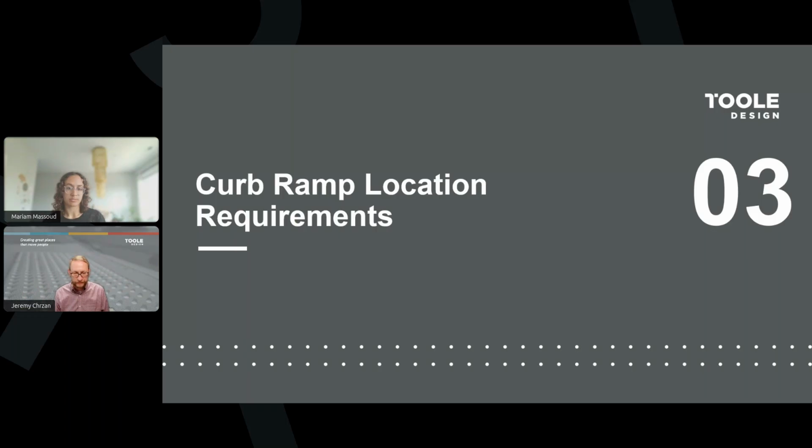Okay. Next question. You guys got a lot of questions on just this first part. What if you have a curb ramp that's on the other side of the widening with no resurfacing? Does the curb ramp have to be fixed? I think what you're saying is you are milling and overlaying adjacent to, we'll call it the departure ramp, but maybe you're only milling and overlaying to the center line of the roadway. That still triggers the need to evaluate the receiving ramp to ensure that the crossing itself is fully compliant.